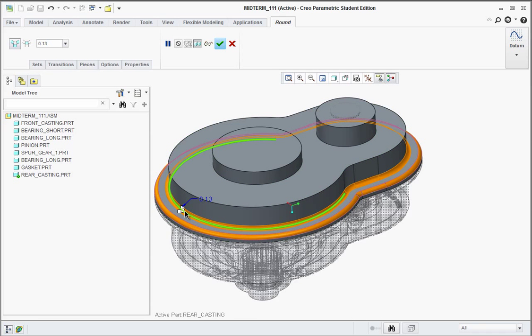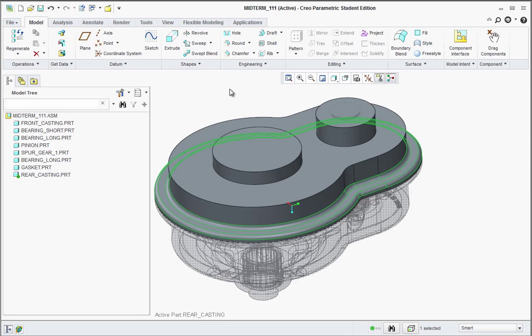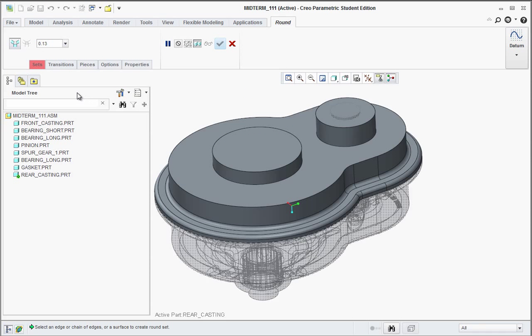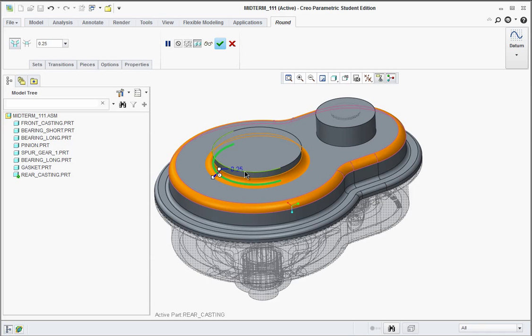Be careful on the print, I don't really call that out. I have an arrow pointing to the flange just on the edge. It says 0.125, but I don't specify the inside edge. The inside edge should be 0.125 as well. Then everything else is 0.25. So this edge here, this one on top, and this one down here.